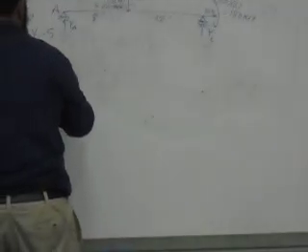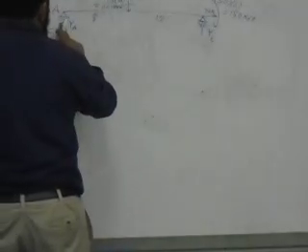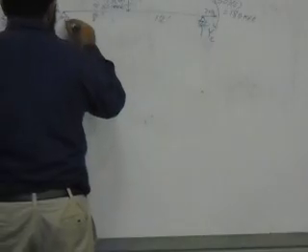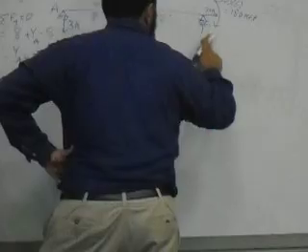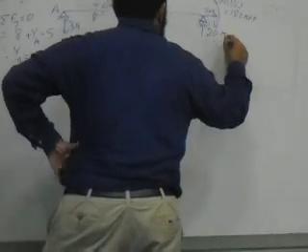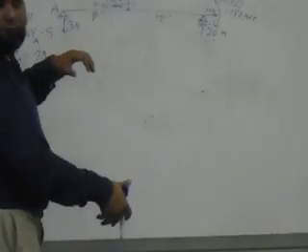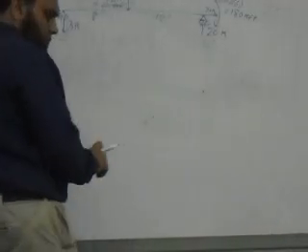Therefore YA is equal to negative 3. This means this thing wants to go down, 3 kips down, and this is going up 20 kips, which makes sense because this thing wants to flip over due to this big moment.